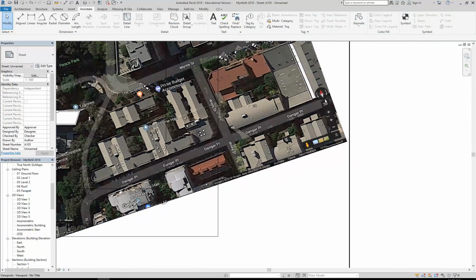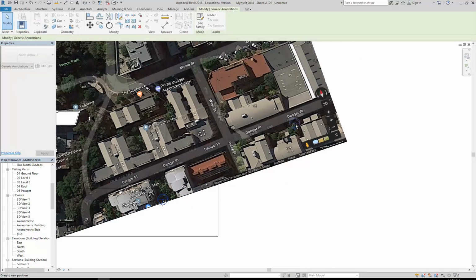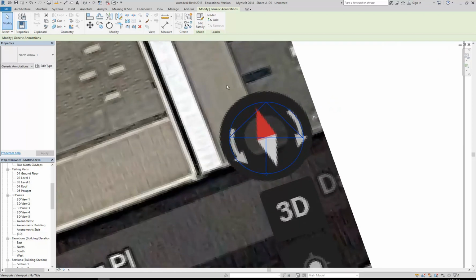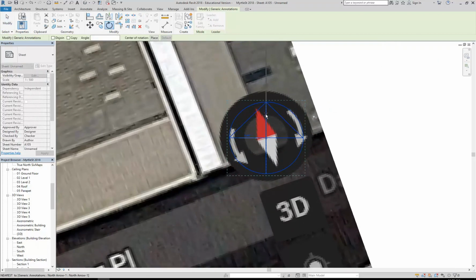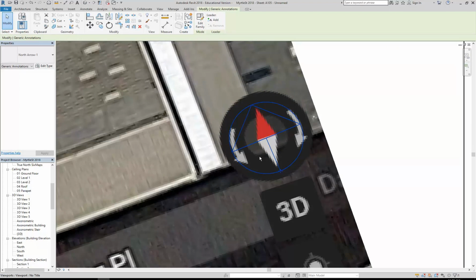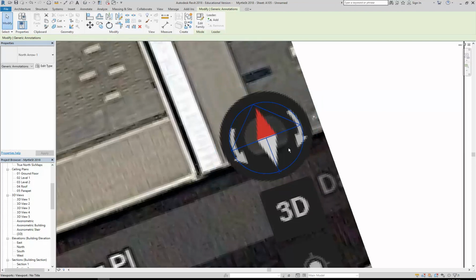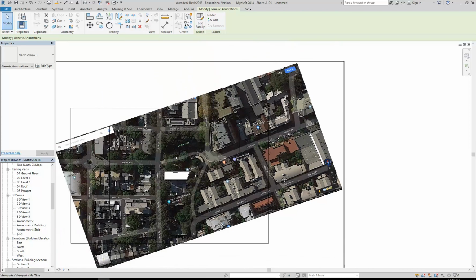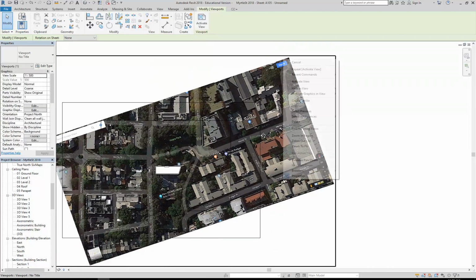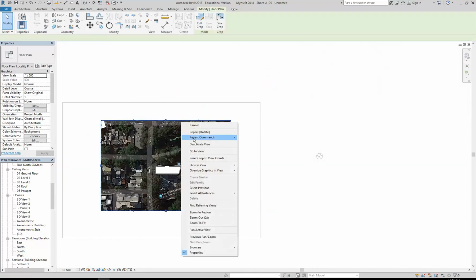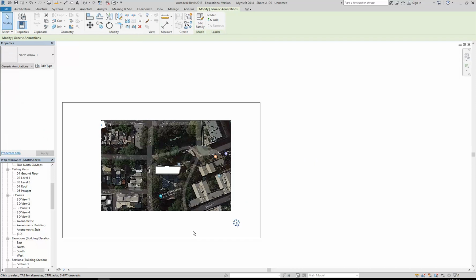You can see now we've got this north arrow showing, so I can drag this somewhere close to it, and then just use the Rotate tool. If I click Rotate, then as long as it looks right, it is right, basically. That's probably close enough, but if you're fussy like me, you could rotate it a little bit more. I can't help it. Good enough. Okay, so now I'll crop my view again and deactivate it, and then drag them all back onto it.